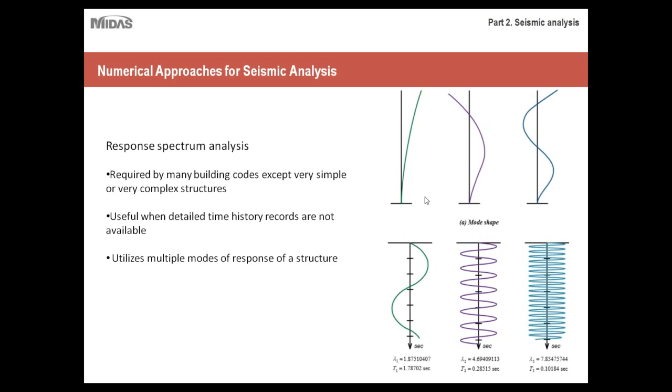So the purpose of these modes is to take each situation into account. As I said before, because seismic loading is cyclic, the forces acting on your structure will behave very differently. It'll vary from second to second. So what you'll do is take three critical modes, three critical conditions upon which the loads are acting on your structure, and perform the calculations for each one. As you can imagine, the displacement for this one would be completely opposite from this one. But both of these conditions are very realistic and very probable in the event of an earthquake.